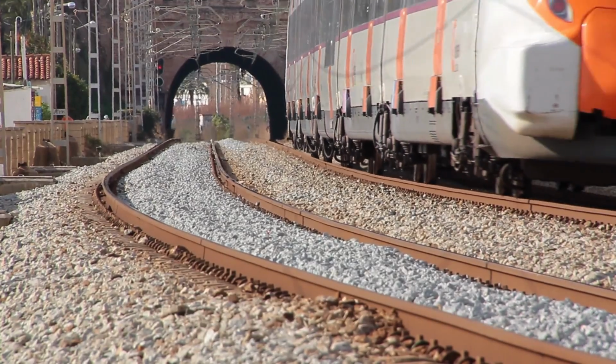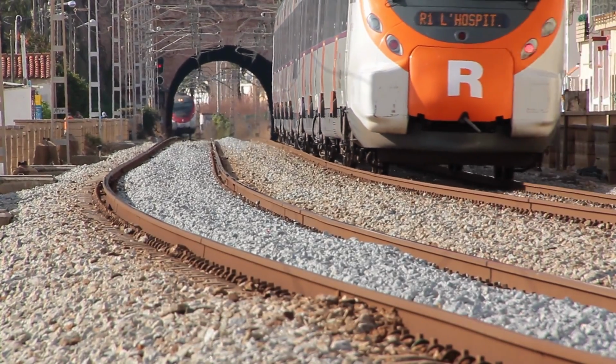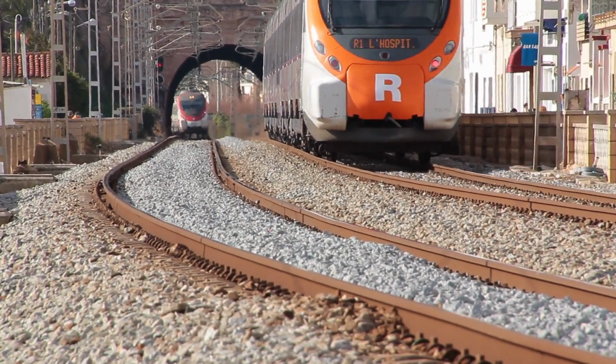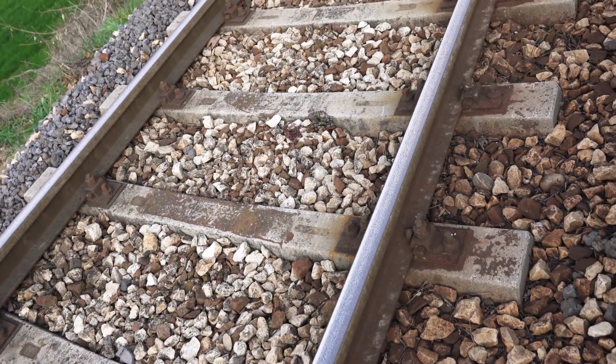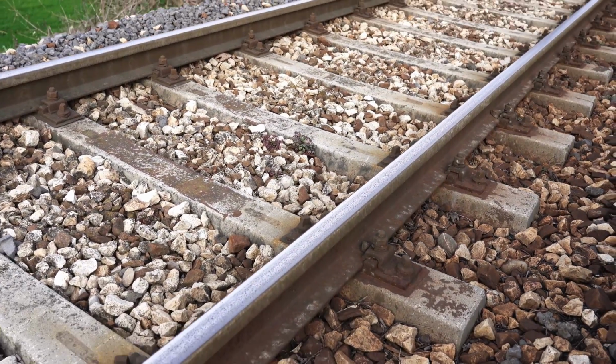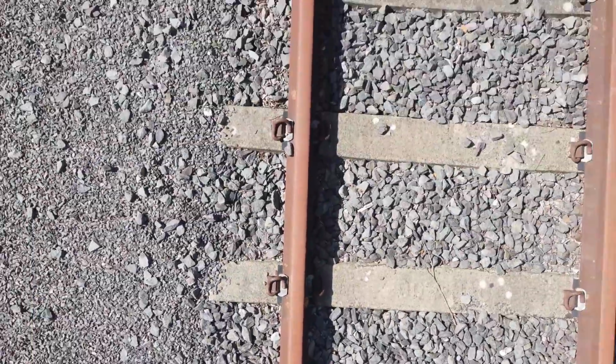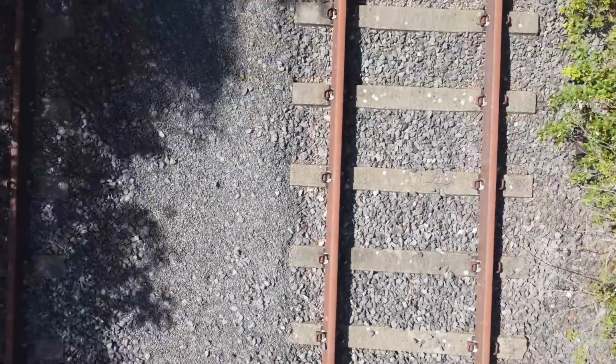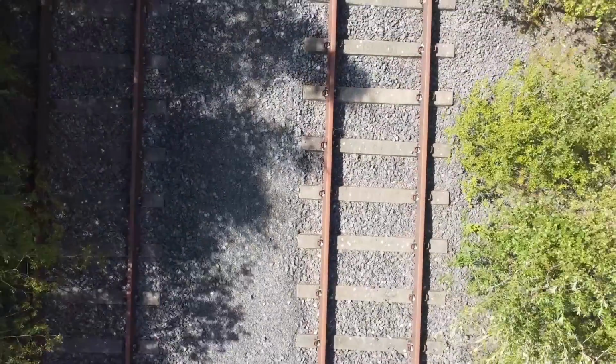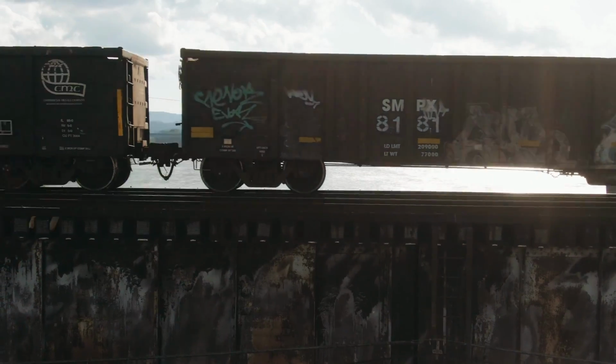Rolling contact fatigue, better known as RCF, is a group of defects that occur on or close to the surface of the rail due to the stresses placed on the steel used to form the rails. Unlike some rail defects, such as tache ovales or longitudinal vertical splitting, RCF defects are not inherent from the manufacturing process, but are caused by the passage of trains.